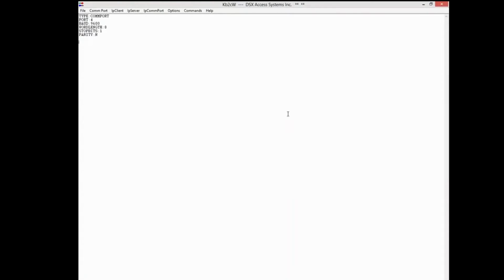If you receive a message that says the port cannot be initialized, there is a hardware problem with the PC that must be resolved. Press the Enter key 3 times. If properly installed, the master panel will reply with a DSX prompt. This DSX prompt confirms that you can communicate to the panel on the defined COM port.